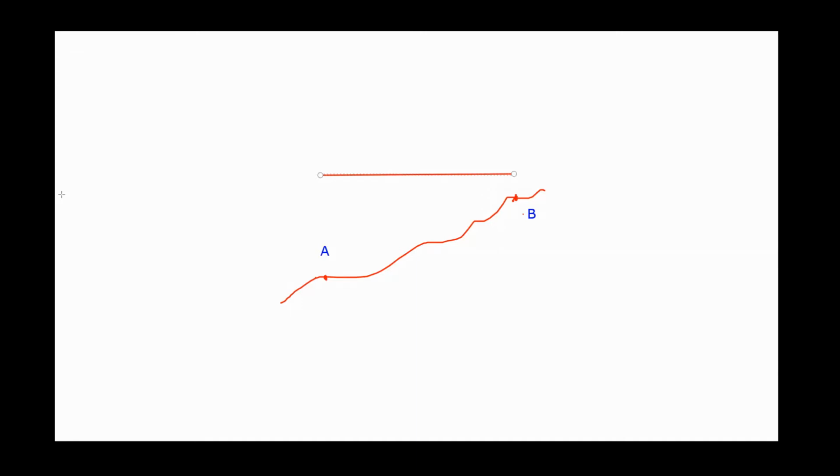We also have a technique called stadia or tachometry, which we will be showing. We don't really use substance bars anymore, and taping is the main focus of this class. So make sure when you measure that you are referring your measurements to the horizontal distance, unless otherwise required.